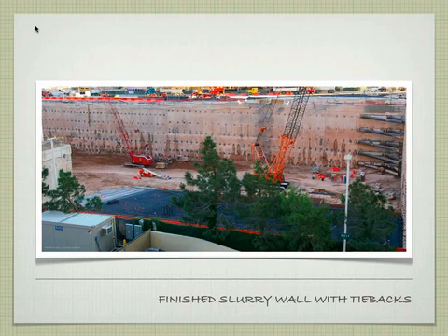So they don't have to go too much deeper than your excavation would be. Those are pretty strong walls. They're very strong walls, which is why you could eventually build your building on top of those walls. It's basically a concrete retaining wall. You're just constructing it from the surface rather than digging and then forming and then pouring the concrete, which we'll get to later on.